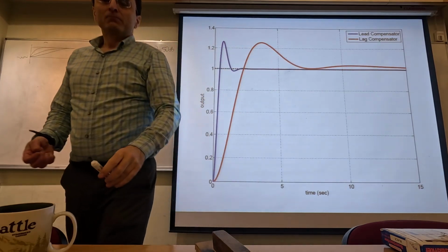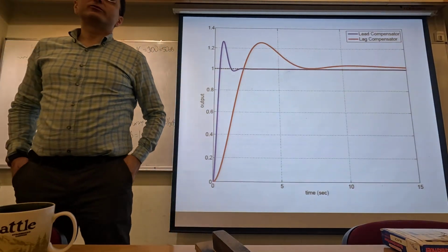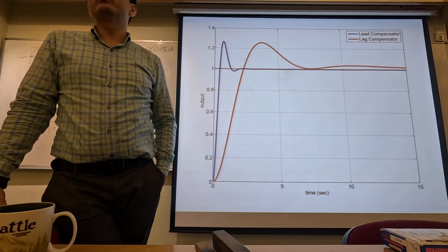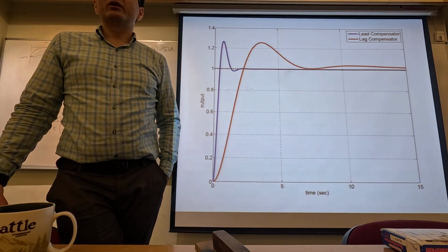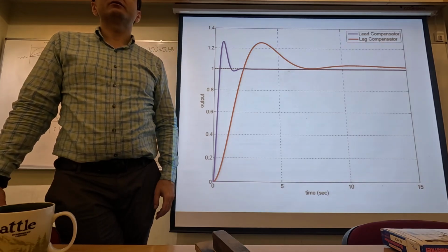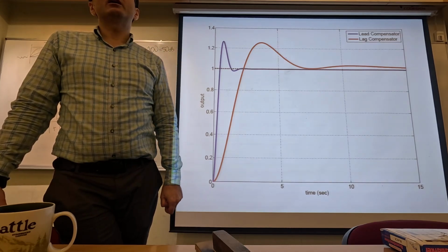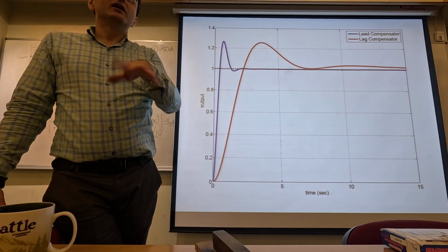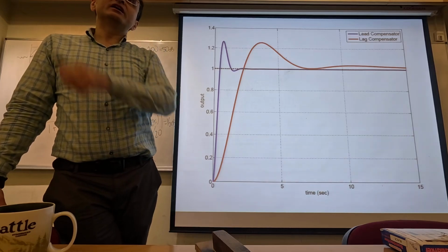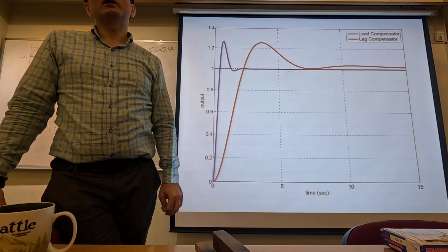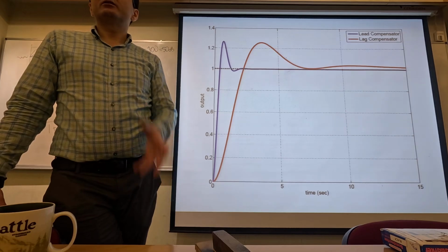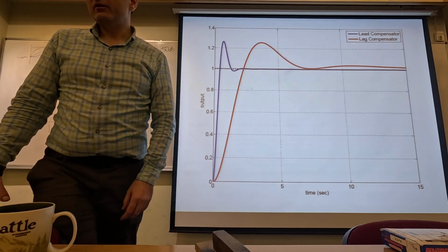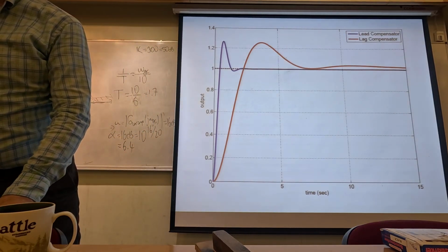This is also the reason why PI controller is used much more than PD controller in control systems with some noise. In power electronics, for example, if you want to control an electric motor, usually you choose a PI controller over PD controller. Because PD controller, because it has a derivative inside, it amplifies noises. A similar thing happens in phase lead compensator as well. Okay? So you choose lag compensator, which is more like a PI controller in your system, rather than lead compensator if you have more noise in your system.